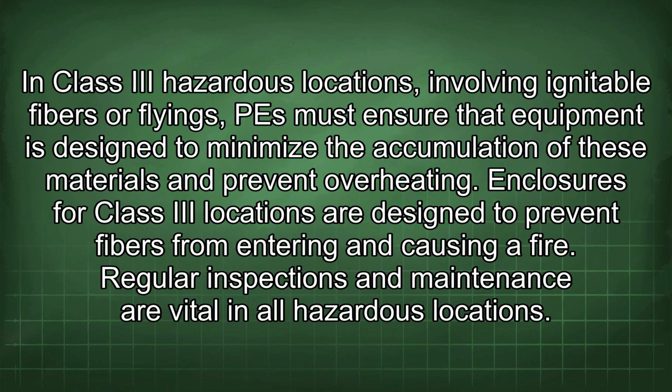In Class III hazardous locations, involving ignitable fibers or flyings, PE must ensure that equipment is designed to minimize the accumulation of these materials and prevent overheating. Enclosures for Class III locations are designed to prevent fibers from entering and causing a fire.